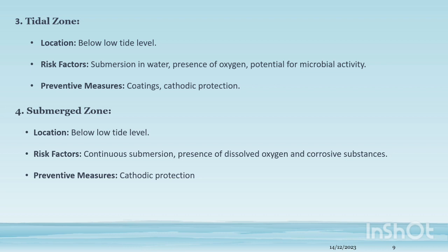Tidal zone. Location: below low tide level. Risk factor: submersion in water, presence of oxygen, potential of microbial activity. Preventive measure: coating and cathodic protection. Submerged zone. Location: below low tide level. Risk factor: continuous submersion, presence of dissolved oxygen and corrosive substances. Preventive measure: cathodic protection.